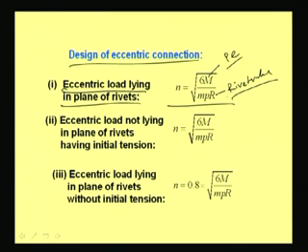Now, p is the pitch, that pitch also we can decide, means if nothing is given then we can assume some pitch. Suppose we have a connection given, so we do not know what will be the number of rivets. So, to start with we can assume some pitch and edge distance, then on that basis we can find out the value n. The moment we find out the value n, what we will do? Then we will go for this edge and pitch and its details.